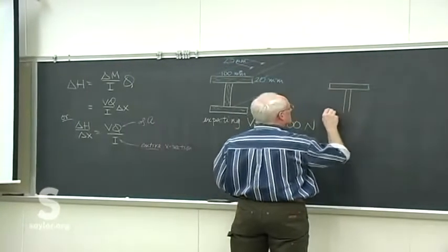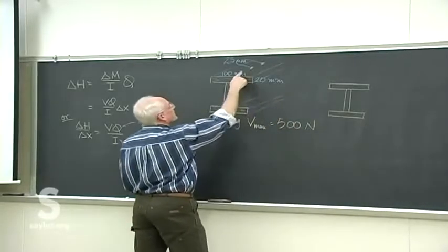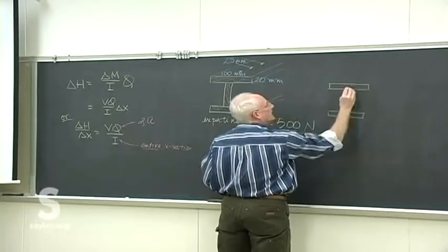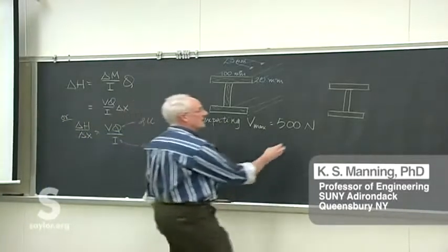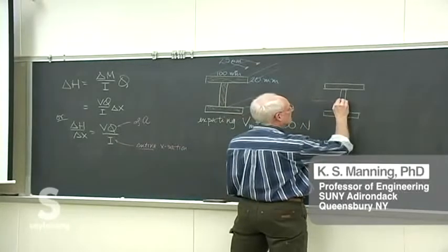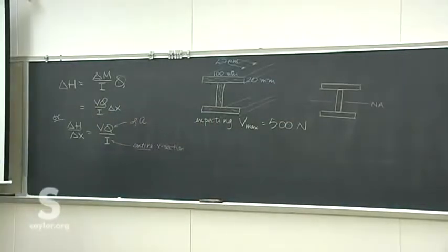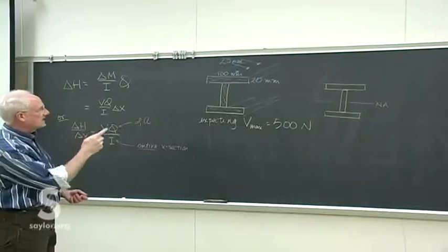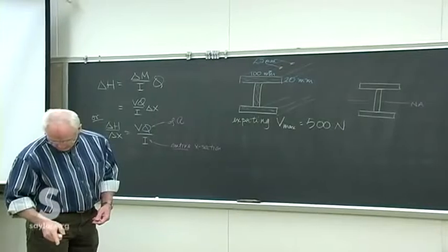All right, so our beam in cross-section looks like that, and we're worried about the nails withstanding the shear at that interface there where the two planks are put together. We don't need to do the other side because it's symmetric about the z-axis. We don't need to figure out where the neutral axis is, by symmetry. We know it's right down the middle because it's symmetric not only about the y-axis but also about the z-axis. So we've got all the little pieces we need.